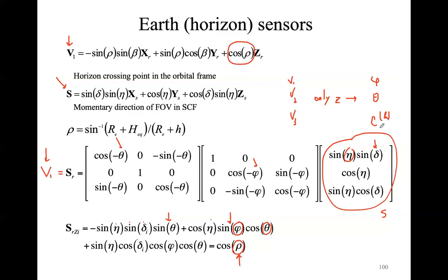That's the reason why a dual scan Earth sensor gives you more redundant information, because you have 4 vectors. But as I said, it is important, especially when one of the crossing points is occulted or there is interference from the light of the moon or the sun. Hopefully, this explains a little bit better what we said yesterday. But let me know if you have any questions before I go ahead with the sound sensors.